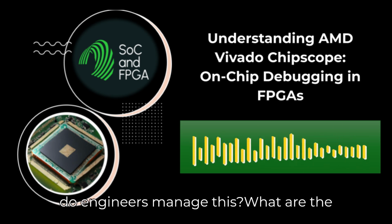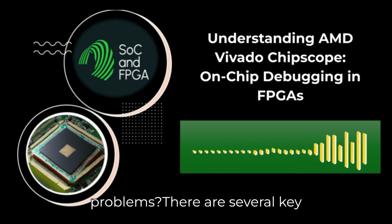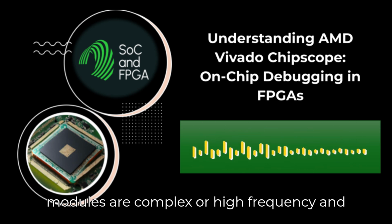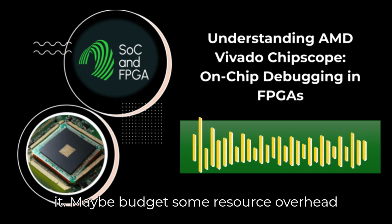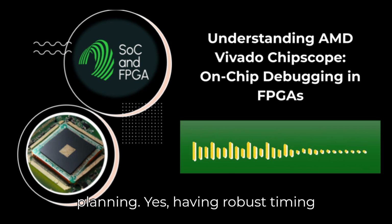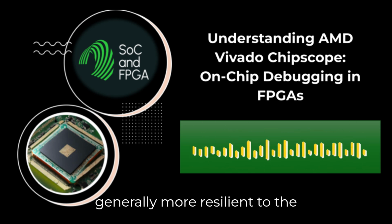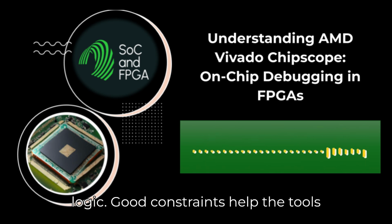So how do engineers manage this? What are the strategies to mitigate these timing problems? There are several key strategies. Ideally, you design for debug right from the start. If you know certain modules are complex or high frequency and likely to need debugging, you plan for it, maybe budget some resource overhead in those areas early on. Proactive planning. Yes. Having robust timing constraints in your XDC files is also crucial. Well-constrained designs are generally more resilient to the perturbations caused by adding debug logic. Good constraints help the tools cope.